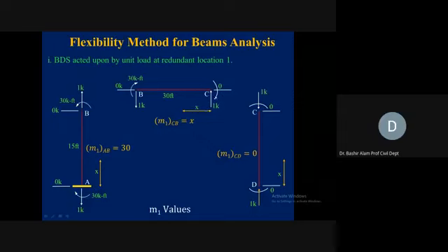We cannot apply the moment at the free end, because it has to be resisted there and it does not have the capability to resist. So the only point where it can be resisted is joint B. How much is the couple? The couple moment is 1 times 30, and it was causing a couple in the counterclockwise direction. So it has to be resisted by a moment of 30 kip in the clockwise direction. Here we show the 30 kip moment.